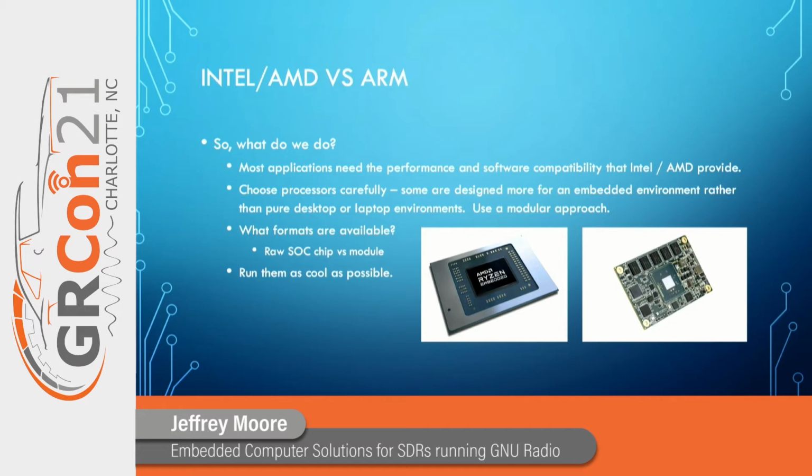And the chips that do that power management are usually only made by one or two companies in Asia. And sometimes they're hard to get and they won't sell to small companies or even medium-sized companies. They'll only sell to giant companies like Asus or somebody who makes lots of desktops and laptops. So it's very hard to design an embedded system around a SoC. It's doable. We've done it, but it's very difficult. And then some of those chips go obsolete and some are difficult to find over time.